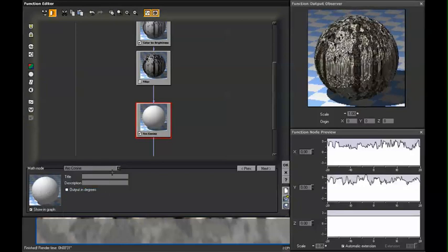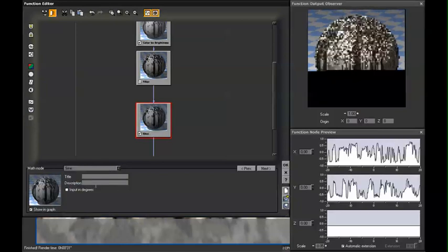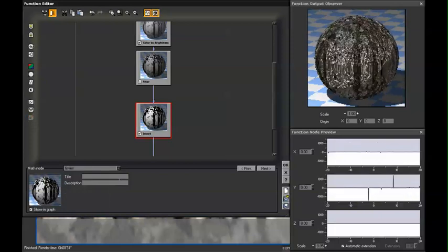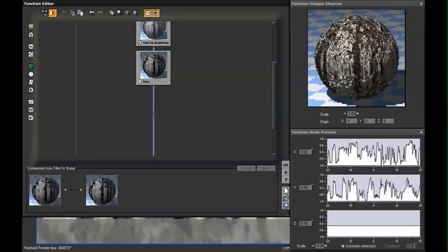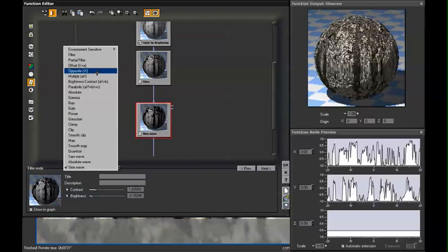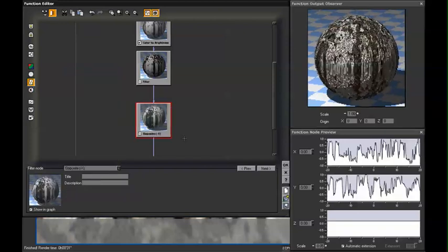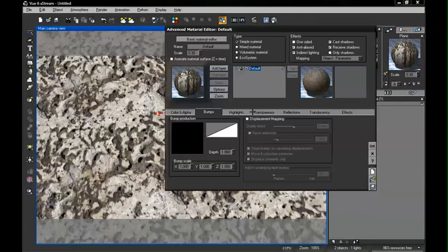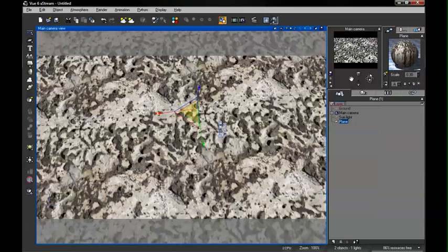We can do the arc cosine function, just a sine wave, and we can also invert that, so we're working with an opposite effect. Although invert doesn't always completely invert the surface to look maybe the way you wanted it, so sometimes you can just use the filter, go to opposite X, and that will give you something a little bit different and more of an actual inverted value. And I do want to reduce that bump down to 0.5. Let's go ahead and render that.